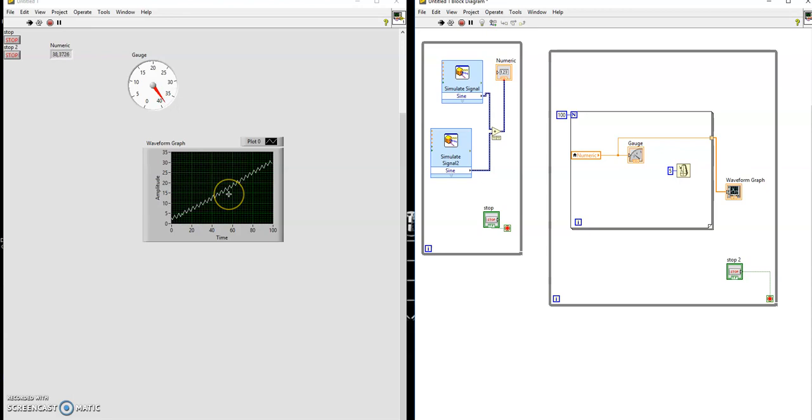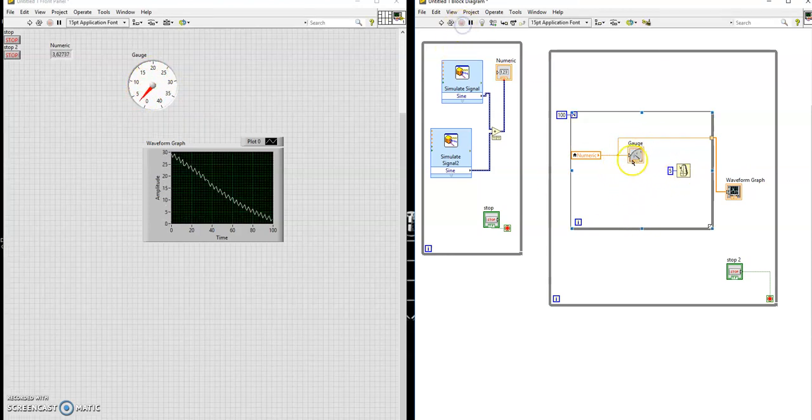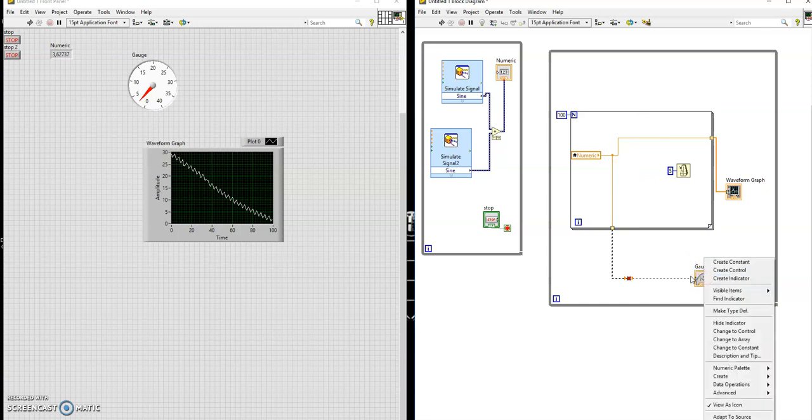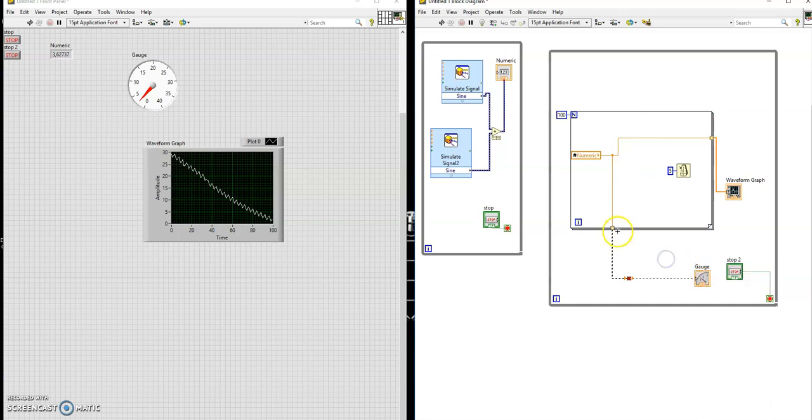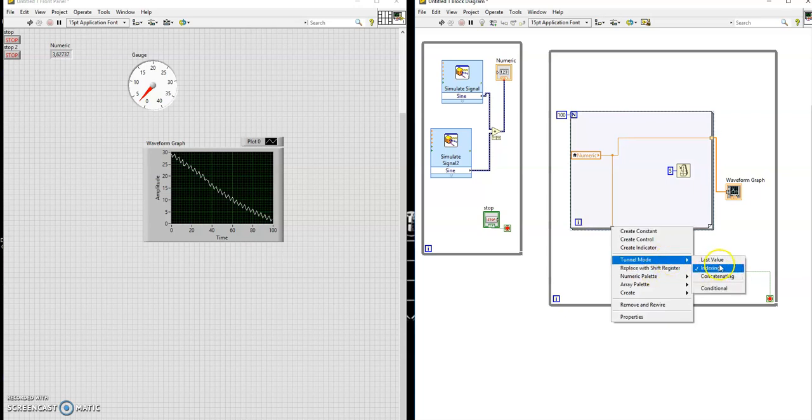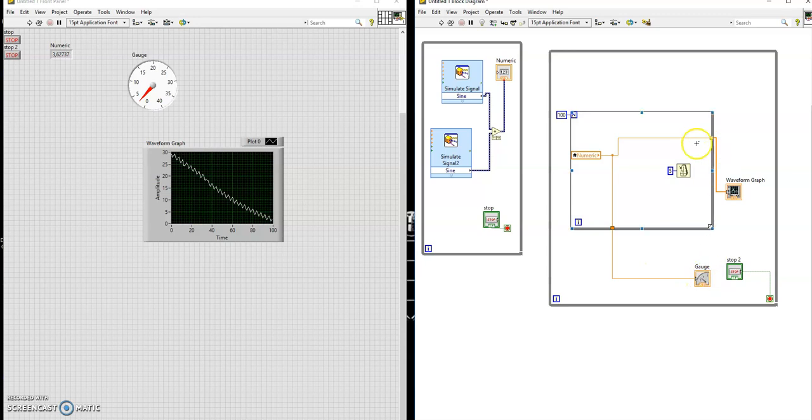It looks like it's real time, but it's really slow. It actually needs to wait for the value. And then that is the last value that's actually happening inside there. If I put it on the outside, it will be much slower. I wire it in there, and I'm going to show you just the last value of the while loop. Just change this to last. Path value. So this one indexes the values, this one makes an array of values.